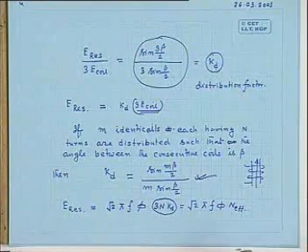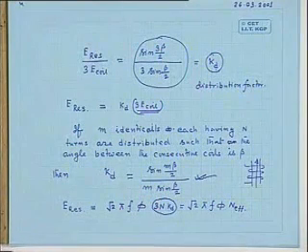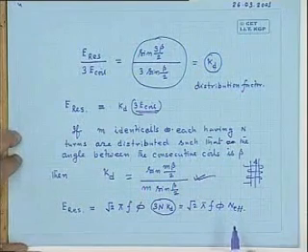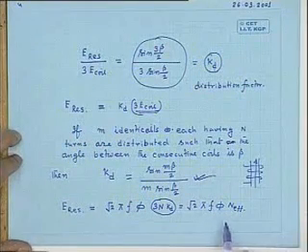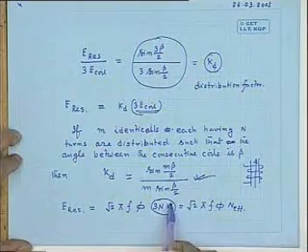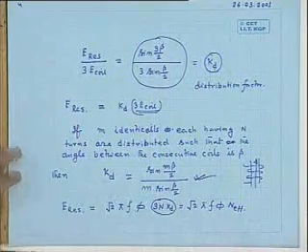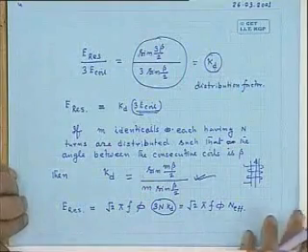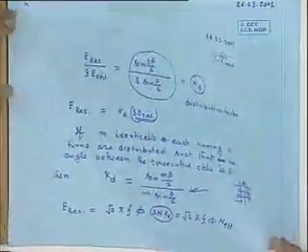Otherwise, suppose you select a large diameter machine and put only one coil, other places remain unutilized. So you are forced to use distributed coils. And the moment you do that, the effective number of turns will be less by a factor called the distribution factor. So the voltage induced in a coil gets slightly reduced.